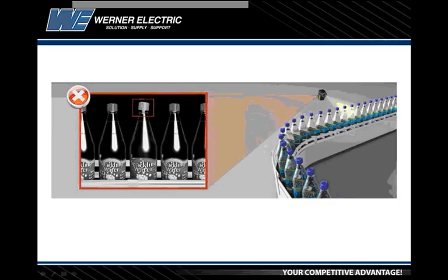Here's another bad product moving by on the line, and this one has a cocked cap. There are two problems with that cap. The obvious one is human health. If a customer got that and it had been open, there could be bacteria in there. But a less obvious one that I've heard about from some folks that do bottling and canning is they call that a leaker.